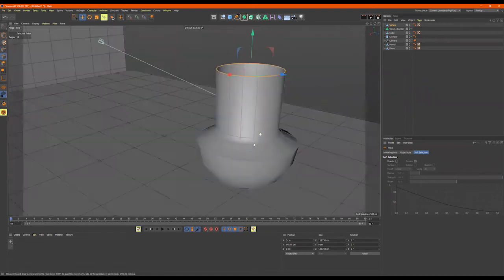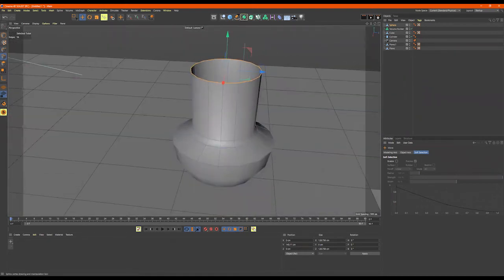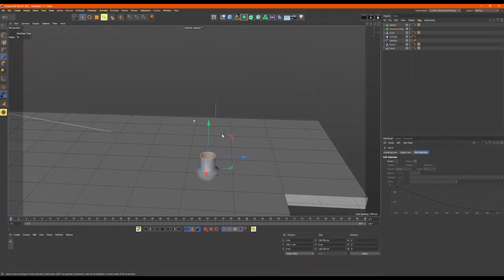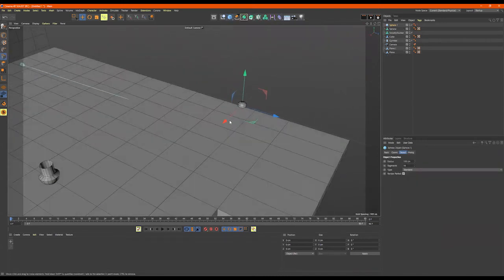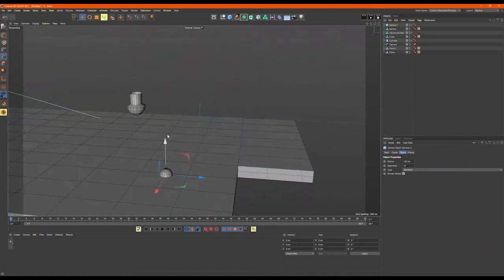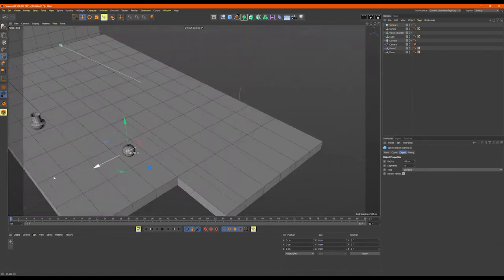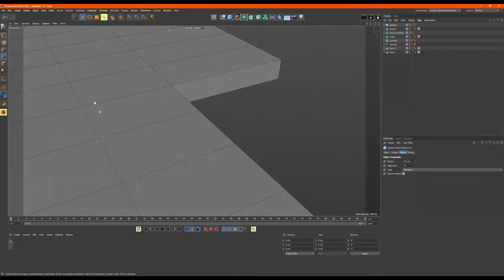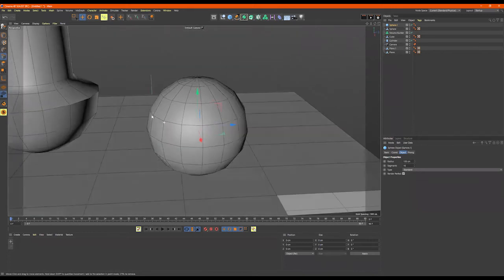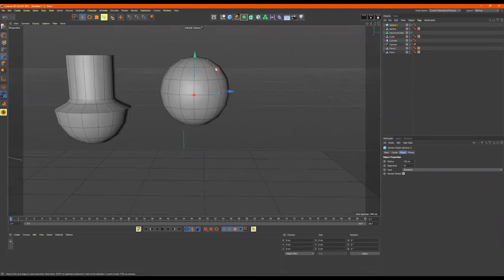Now something else I'll do, since these edges are kind of jagged, I could have gone and got a sphere and added a lot of the loops. Matter of fact, I'll show you how to do that real quick. So this example on subdivision. Just show you how it works. S. So I have this sphere right here, right? Instead of 16 segments, let's change it to, I don't know, 60, a high number.